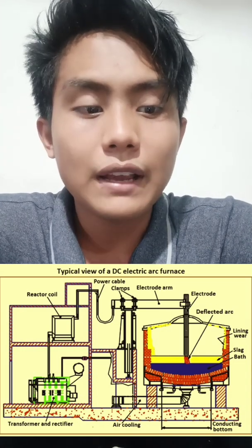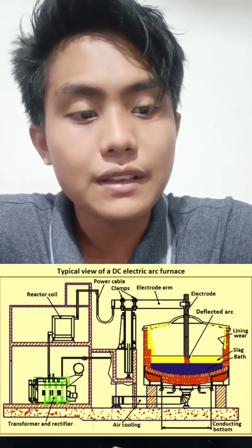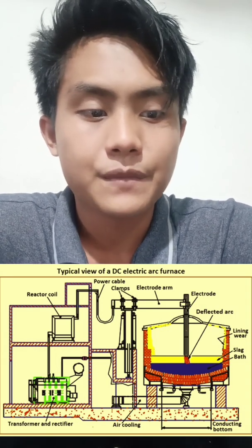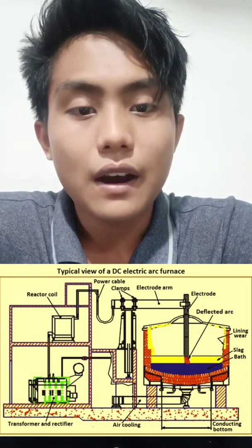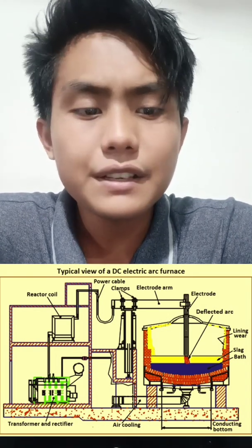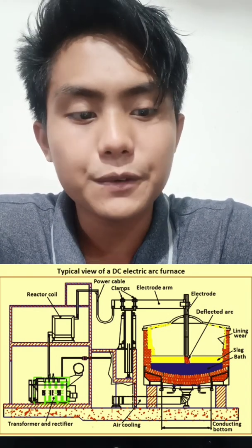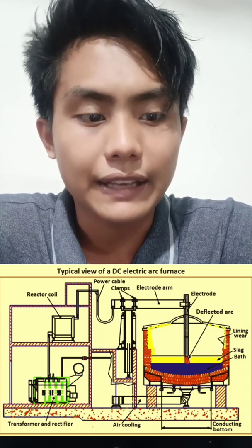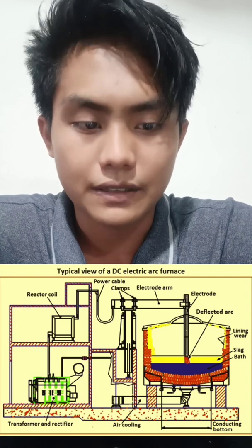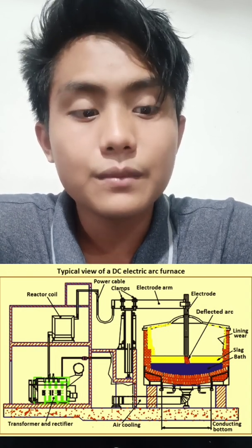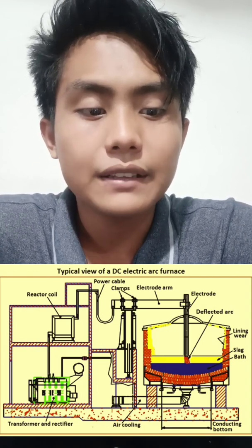To purify the steel, the furnace then blasts in oxygen, and lime and fluorspar are added. These substances combine with the steel's impurities, turning into slag. The slag then floats to the top of the molten steel where it is removed, leaving behind the pure steel.